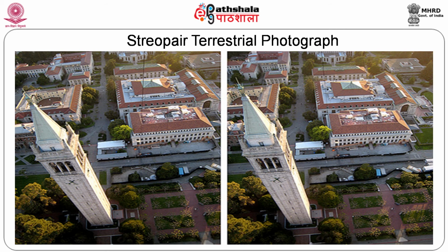Now, coming to how a stereo pair of a terrestrial area in terrain is taken: two photographs, okay. Each of them is taken with an overlap. I told you earlier itself, overlap will be there. So, when I look at this through a stereo mirror, or mirror stereoscope rather as we call it, that will give you a 3 dimension, which is not possible with a single photograph. You will have to have two sets of photographs.